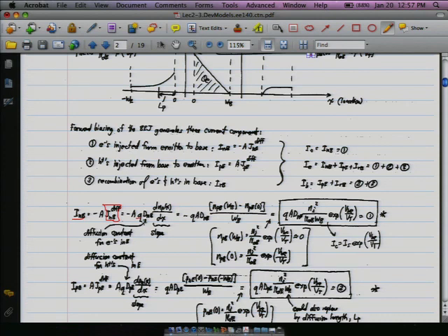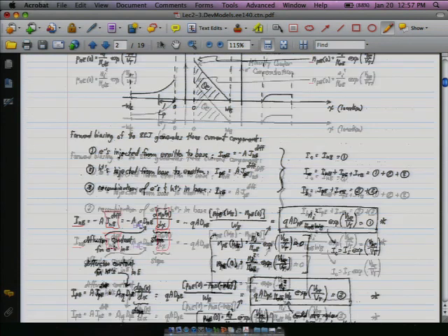And here we have a diffusion constant, which at this point we're not going to talk about where that constant actually comes from, but you can just be assured that it's a constant. So it's this number that basically has been characterized by the device physicists. And then this last term here is really what becomes interesting, which is that we're looking at the change in carrier concentration over this distance up here. So this is where we start to come back to this figure.